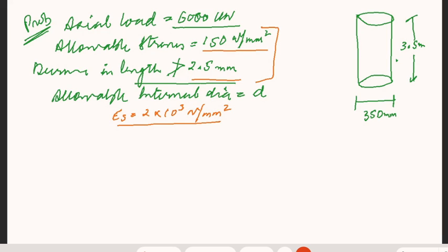Okay. Now, first of all, we have the condition for calculating our strain. Strain is already given. We have a condition which says that stress is equal to modulus of elasticity times epsilon, that is strain. And given the values, we can simply say stress is load per unit area, that is equal to modulus of elasticity times change in length over actual length.